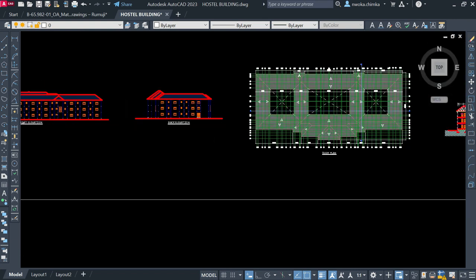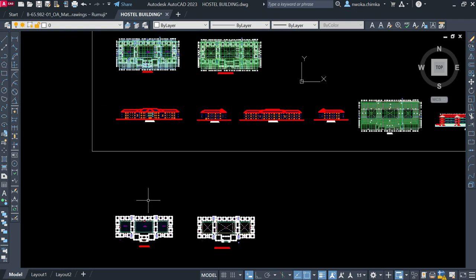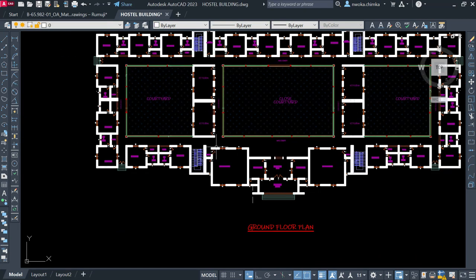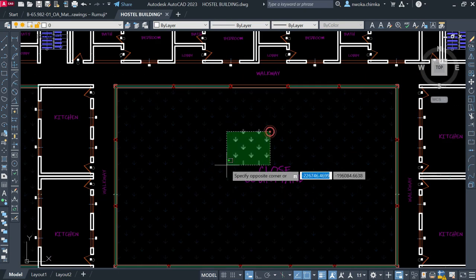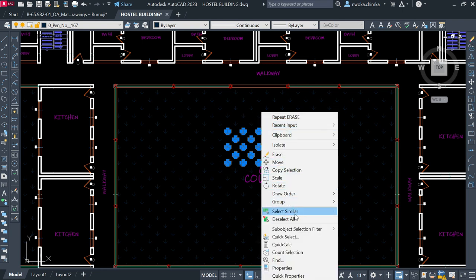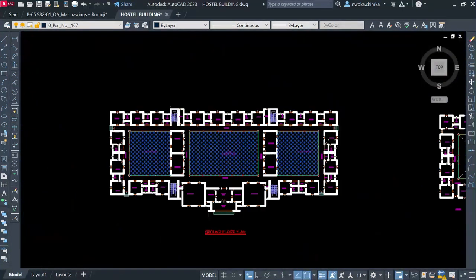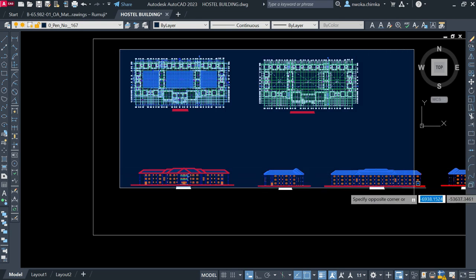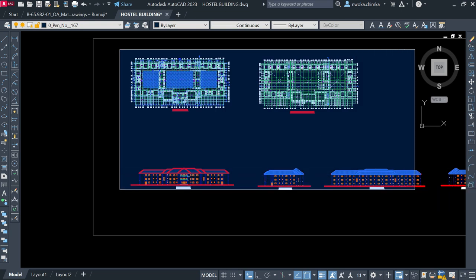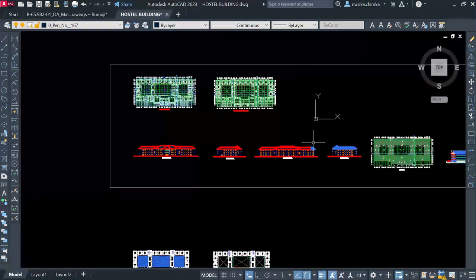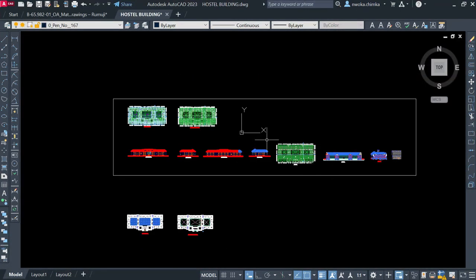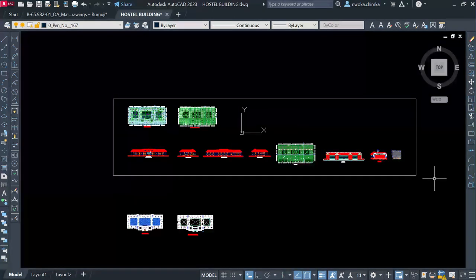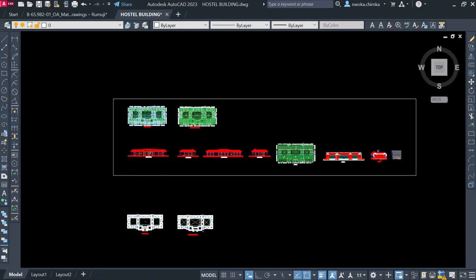Okay, so right now, let me go again and then go back to where we have right now. So this is what we have just done. I also remove this and take this off, and then now I'll also remove this hash. I don't need this hash here, so I'll just right click and select similar, and then I will go again and deselect if I've already selected it here. Okay, so I'll go here and deselect here. Okay, I'll wait for it to finish up and then go again. I think the same hash they use for the roof, I'll also deselect it here. Okay, I'll wait for it to finish up, and then I'll just type E, enter, and you will see it going up here.